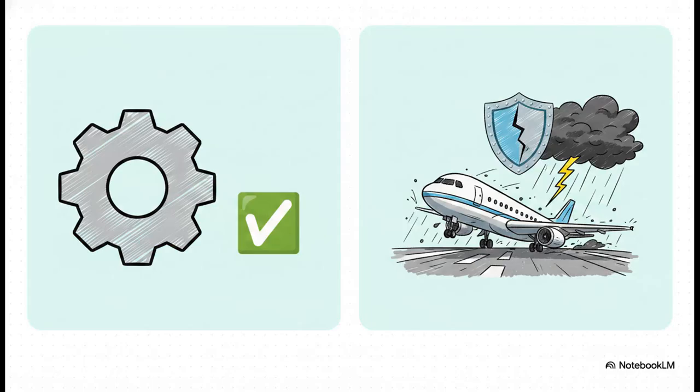And that Warsaw crash brilliantly synthesizes this difference for us. Reliability is all about meeting specifications. Safety is all about preventing harm. In that runway crash, the software met its specification because a built-in safety feature actually stopped the reverse thrust from deploying. Why? Because based on the sensor readings in the storm, the software assumed the plane was still airborne. So the software was highly reliable, but because the specification didn't account for the reality on the ground, it was completely, disastrously unsafe. You absolutely can have a perfectly reliable system that is completely unsafe.